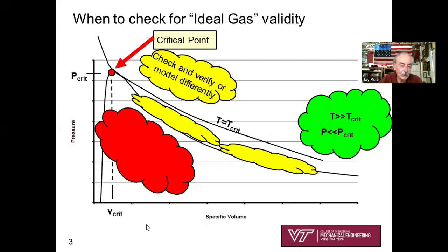All right, I've drawn a generic pressure specific volume diagram. You can see to some extent the vapor dome, it's almost obliterated, isn't it? But you're familiar enough with it. Here I have labeled the critical point on the PV diagram, and I've got an isotherm, a line of constant temperature, going through it, labeled T equals T critical. So that's the critical temperature. This is the critical pressure here. And here's the critical specific volume. So that absolutely pins down the critical point.